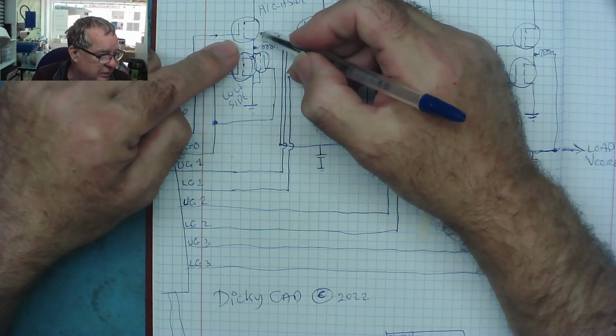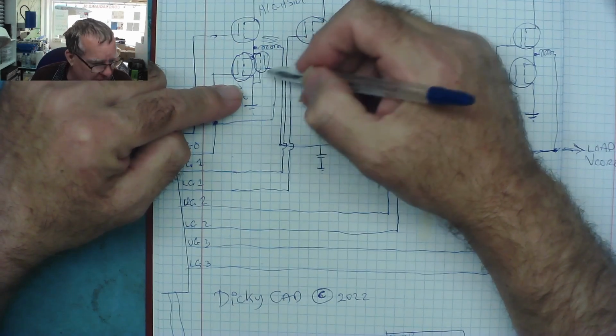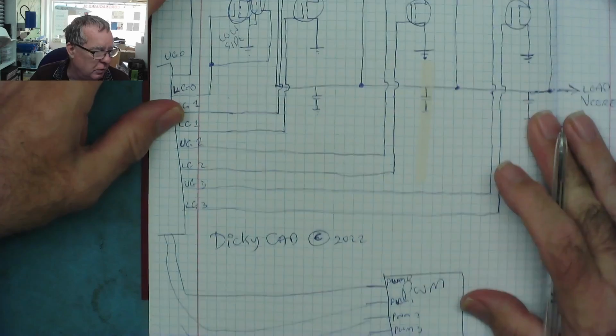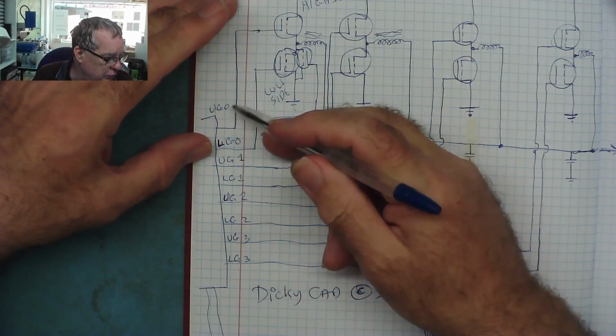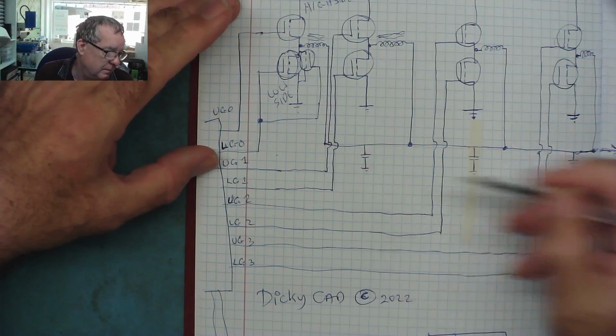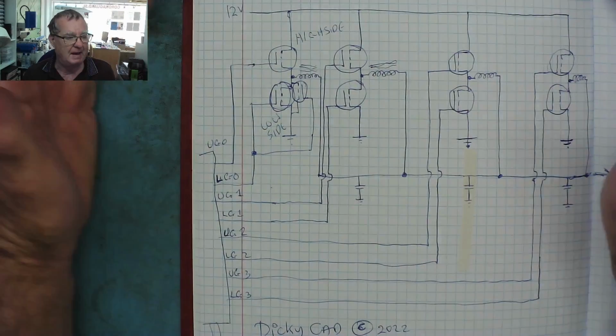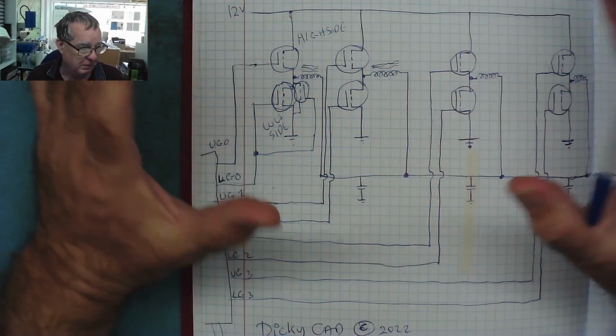Normally this is one type of MOSFET, and these 2 are a different type, but both the same. So in actual fact, what you'll normally find is one pulse width modulator, 4 drivers, one for each set of MOSFETs, and 3 MOSFETs in each phase. That's a very, very common topology that you'll find.